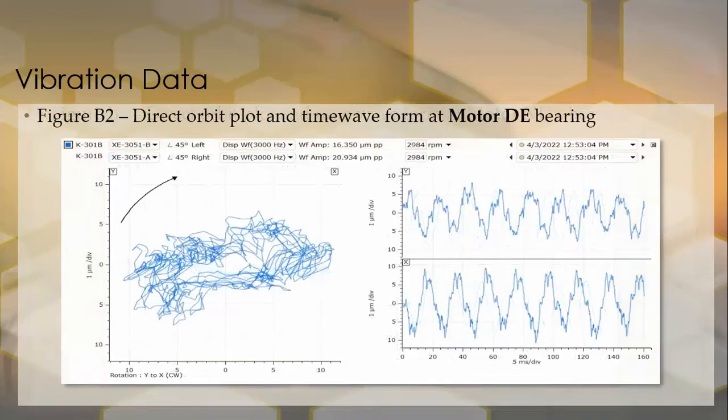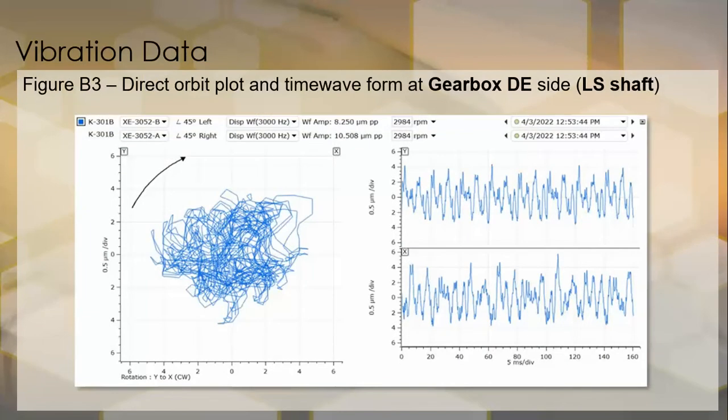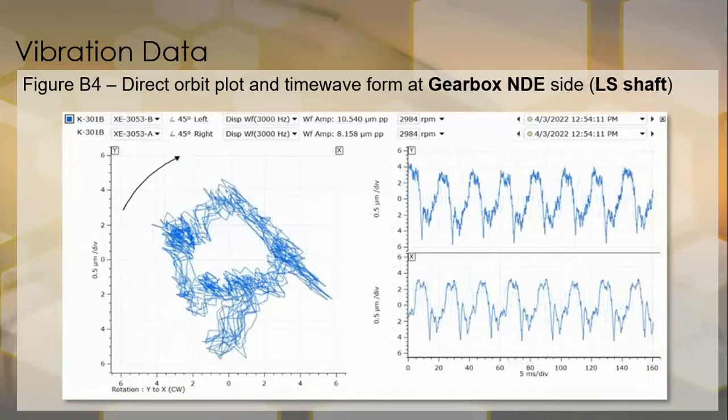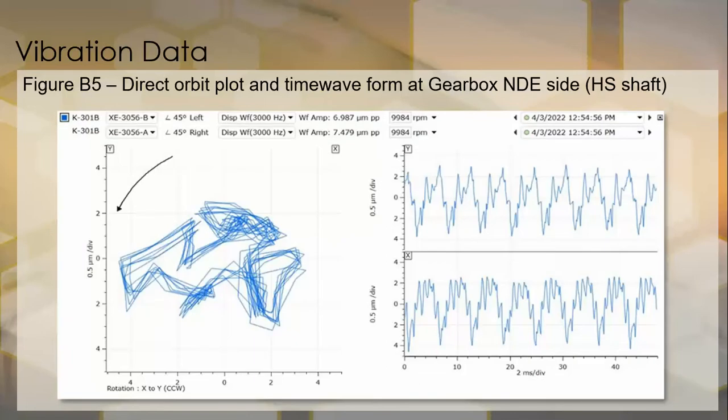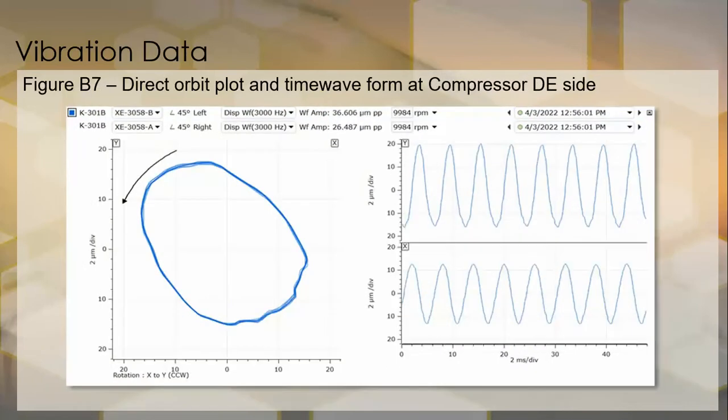As you can see, I'm gonna flip it as soon as possible. If anybody requires a clarification for any orbit shape, spectra, time waveform, or thermogram, you can ask and they will support you, but because we have limited time in this presentation, I'm gonna skip it and just show it to you. This orbit shape, time waveform, and the spectrum showed the suspicion of the unbalanced forces.